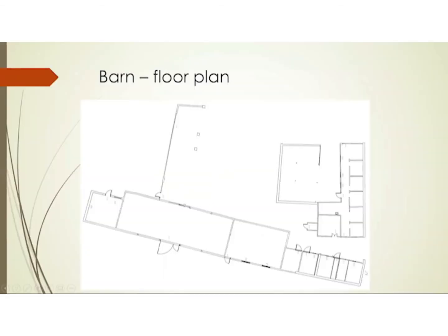The point cloud information can then be exported into drawings that we'd be familiar enough with on CAD. For example, a floor plan. And this is the kind of thing that I think has really usefully been picked up by the laser scan, that these walls are not straight. There's 3 or 4 kinks in that particular wall, and also that it's not parallel to this one. Also that this wall, if I had surveyed this in person on site, probably would have been straight, whereas again there's a kink to it there.